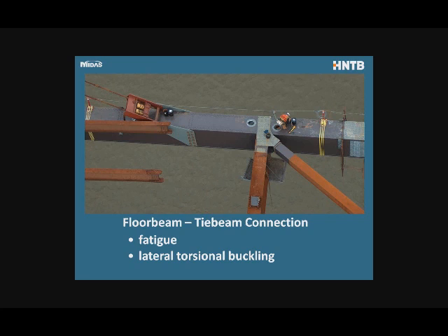But that often leads to fatigue issues because the tie girder wants to move and the floor beam and the deck want to move differently. And what you often see is that the web at the floor beam cracks due to deformation-induced fatigue. So for that reason we connected the floor beams to the tie girders, and it had another advantage, which is with these long beams that are sensitive to lateral torsion and buckling. By holding the floor beams near the ends, we actually improve the lateral torsional buckling resistance of these floor beams.